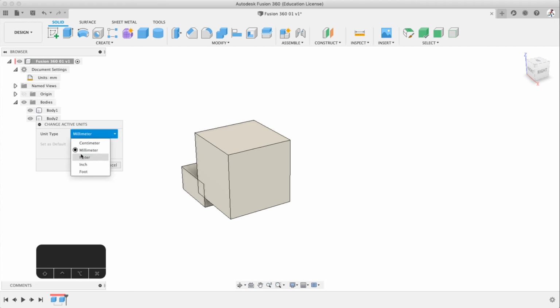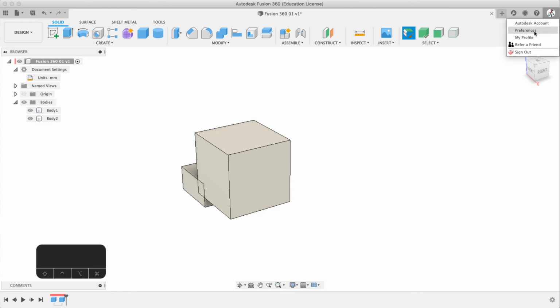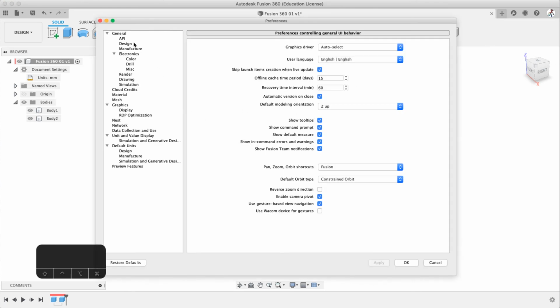So just watch what you're doing here. It probably won't matter, but in the end, you can transfer back and forth. If you go from inches and work for days and then change it to millimeters, Fusion does a great job of doing that. If you want to change the decimal points, you can go into preferences here. When it pops up, it shows you your measurements.